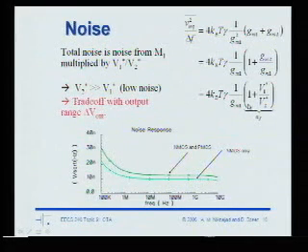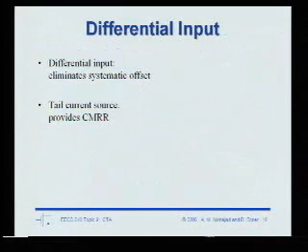And basically, the noise enhancement factor is given by a ratio of the bias voltages, right? The overdrive voltages. So to get low noise, you're going to bias the PMOS transistor with a large overdrive voltage, right? To get good signal-to-noise ratio, though, you have to weigh the fact that signal power goes like the square of V star, right? Whereas noise is just linearly proportional to V star. So clearly there is an optimum point. You don't want to make V star too large, because then your signal is going to suffer. Okay. All right, I'll stop there.